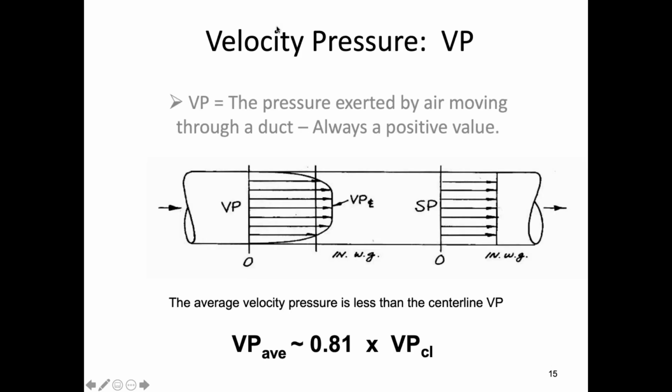We measure velocity pressure by putting a device into a piece of ductwork called a Pitot Tube. This is a Pitot Tube. And one of the properties of velocity pressure moving through ductwork is that it doesn't move through the ductwork uniformly. If you look at that, can you see that, by the way? I've got to get that thing out of the way, make it a little easier. Okay. So you notice that cone over there?